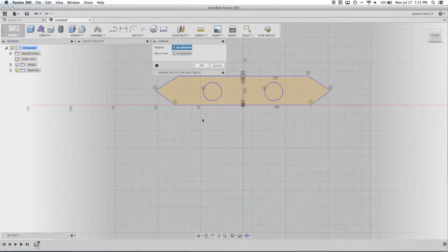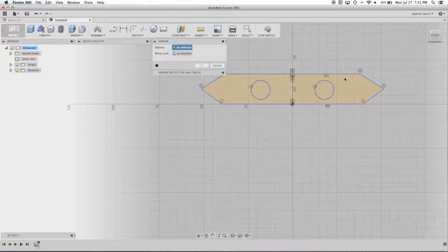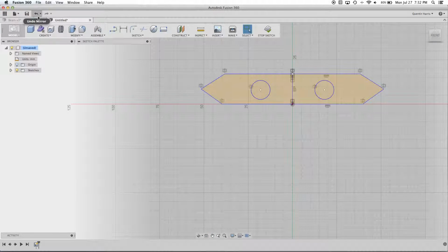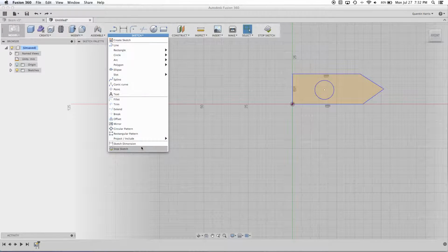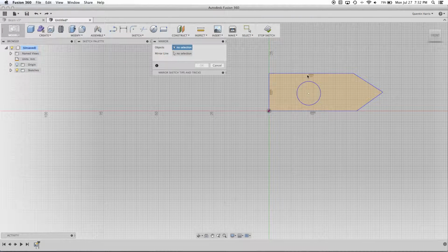And once again, to show you how that worked, I just selected the lines on my first sketch, except for the line that I wanted to mirror across, because this doesn't work for mirroring for some reason.